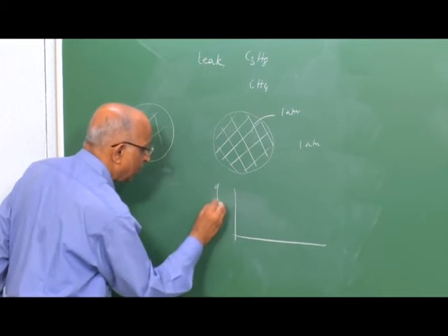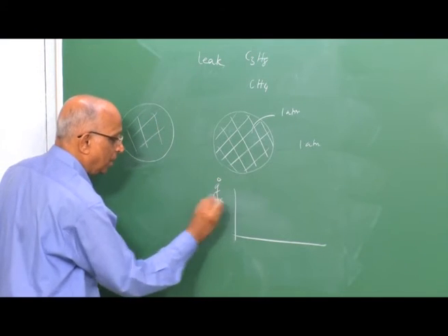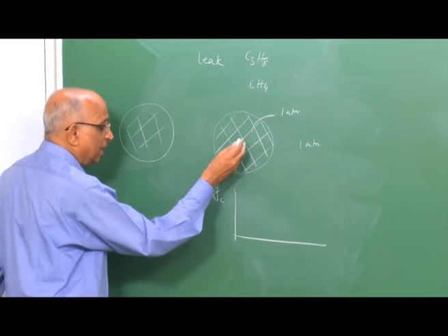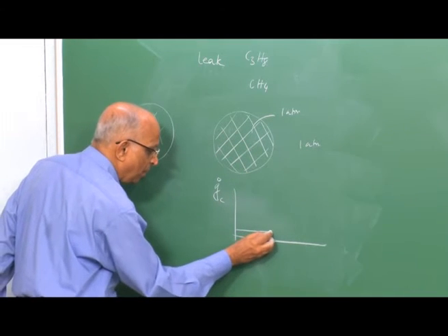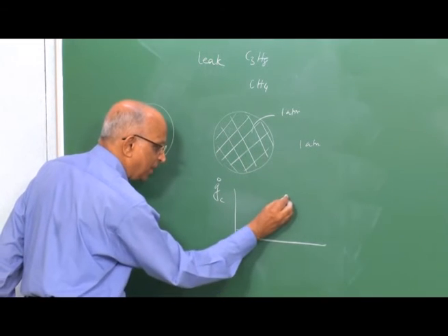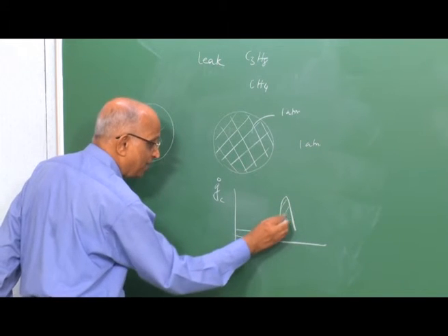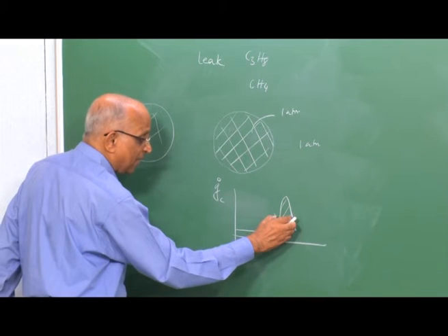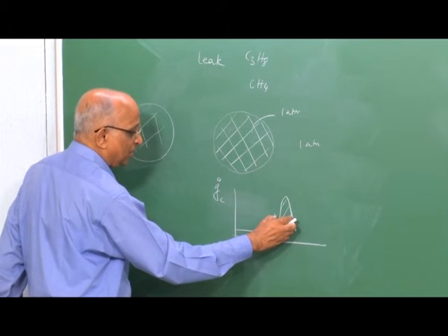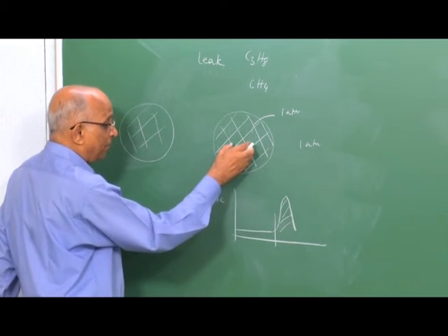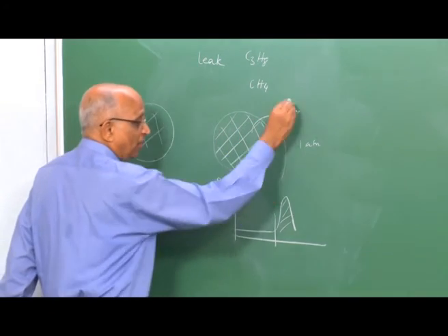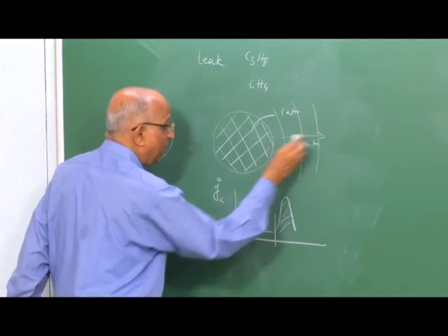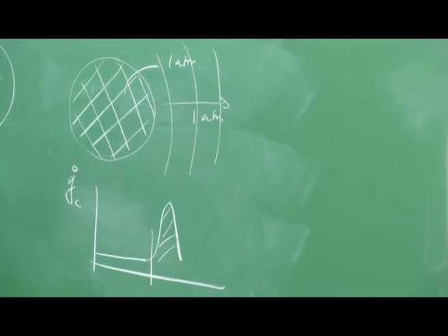the heat release from this particular cloud. What happens? Initially I have an induction time, followed by the induction time I have a spurt in the energy release. Because I have this spurt in energy release after this induction time, and this chemical reaction time during which actual heat release takes place is very small, what happens is that because of the spurt, blast waves are generated and you can have an explosion even in an unconfined environment.